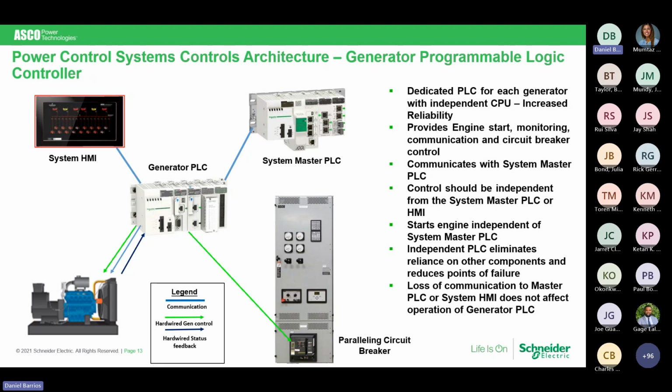But when you look at the engine start and monitoring, we will typically tell you that we're going to give you one set of contacts that will be through our monitoring system to meet that NEC requirement. We would typically then have a second set of start contacts that are wired directly into our PLC as a hardwire backup should you lose that communication also through the monitor system. The controls should be independent from the master PLC. Yes, they are. We'll talk about that.